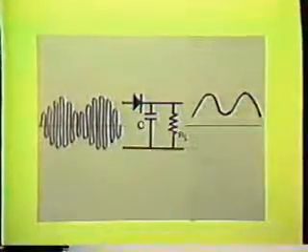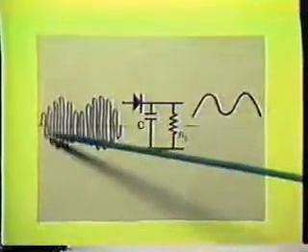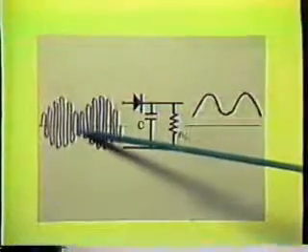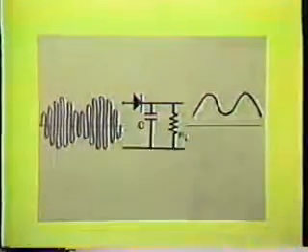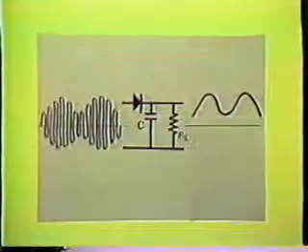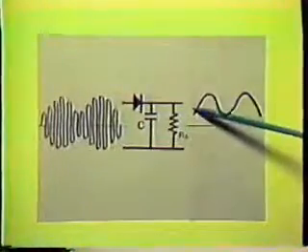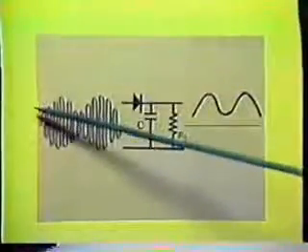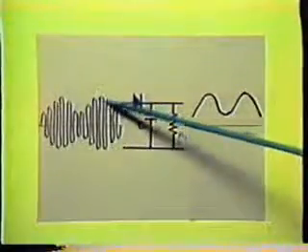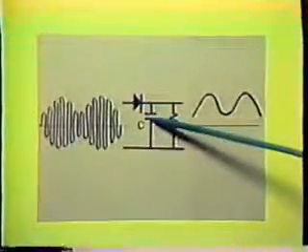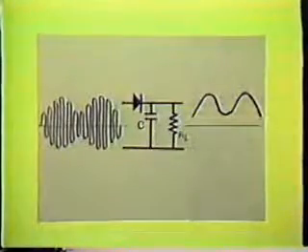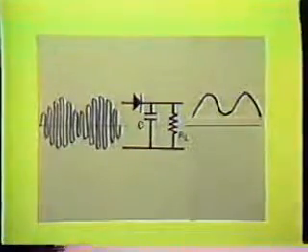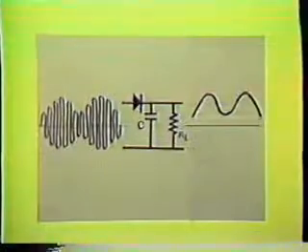The diode will be reverse biased and will not conduct during the negative half of the modulated signal. The output of the detector will be a rectified signal, which will vary at the rate of the modulating signal. The capacitor serves essentially the same purpose as it did in the power supply. In the detector, it removes the high-frequency ripple from the carrier.